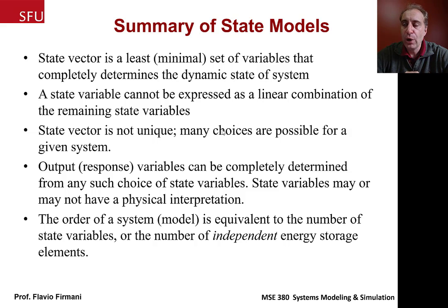So we're going to see, I'm trying to make a couple of examples where the method is going to be completely different. We're using the physical approach with the through and across variables, and we can use the mathematical approach. And the state variables are completely different. In one case, we have forces and velocities. In the other case, we have displacements and velocities. But the response of the systems is going to be the same.